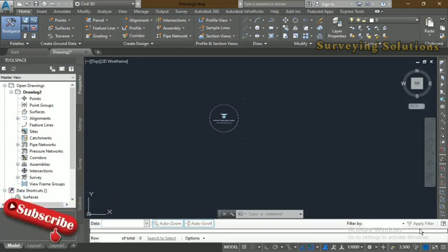So the first thing is that we want to move the PDF drawing file to AutoCAD. There are different methods of doing it. That's the beauty of surveying. One can achieve a particular result in one way, and another person can achieve that same result in another way, because there are different software and different methods. So now you can either type import, or you go towards the Insert tab.